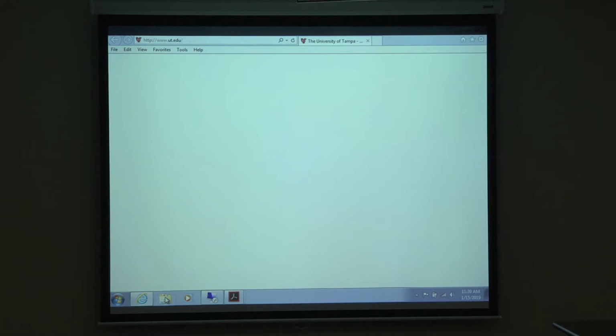And Polaris is pulling from the SSU server, so you're pulling all that information back to your front end, right? And there are two ways you can log into the site. You can log in using a local copy of Polaris, which means that you just enter the IP address of the server. Remember I said the server has two NIC cards, network cards, right? One of them is connected to your building network, and one is connected back to the ECUs, right? So the ECU connection is on a standalone network called a 172 network, right? But the 10, what's the other one called? Let me see what it's called.